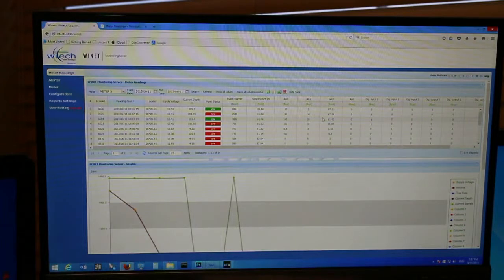Okay, so when you're doing 3G, it's not that costly, but using satellite, it's going to cost you more if you send this information when you don't have anything there. So that's why we set that up. Also, reading analog and digital inputs takes more time, and more time means more energy, and we want to save as much energy as we can. So that's how it works here.